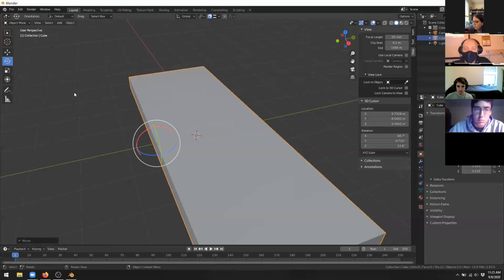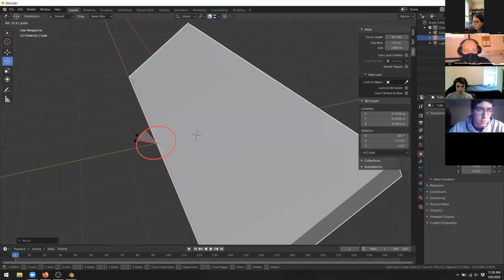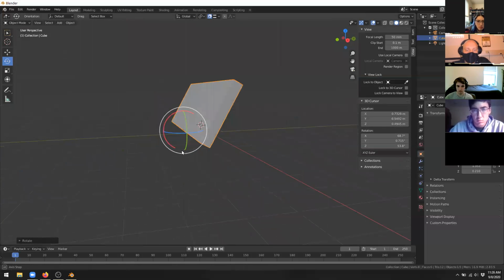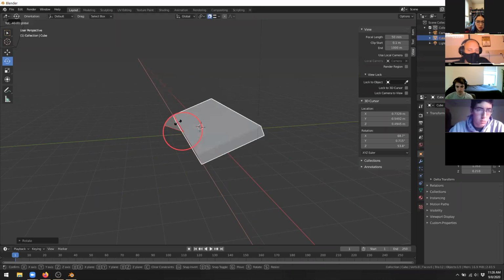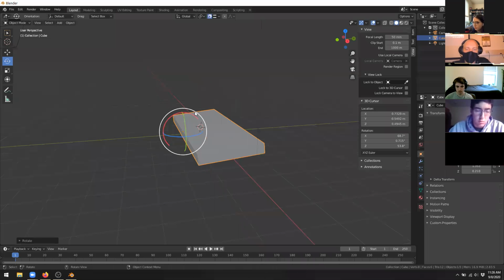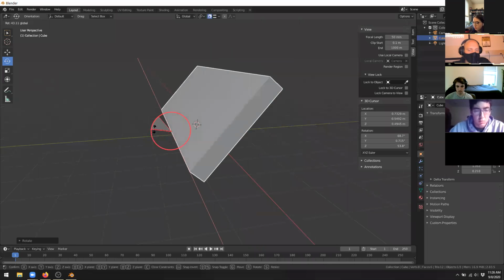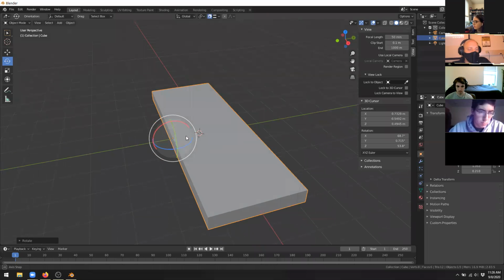And so at this point in time, if I switch back to my rotation tool and rotate it along that particular axis, my object will indeed rotate off of that origin point as opposed to its center point. And the benefit now to that is I have a simple motion path where my object behaves differently than it did in its default state. So it's kind of a small thing, but obviously this is something that'll certainly come up. There's a number of different examples where being able to rotate and pivot objects off of other points besides their default centralized origin is going to be useful.